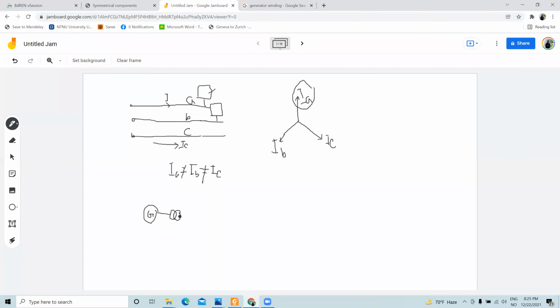But the transmission network has much higher voltage levels, which can be 132 kilovolt, for instance in Bangladesh, or 230 kilovolt, or 400 kilovolt in our country. So these are the different voltage levels. You can see that the voltage is much higher than the generator terminal voltage. As a result, you need a transformer to step up the voltage to the transmission level, and then you transfer this using the long transmission line that you basically see.